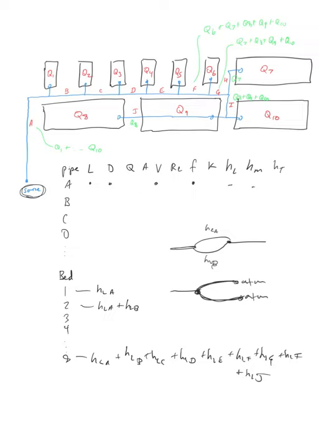What do you do in reality to combat that? Lots of things. You can change the design of the way the pipelines run. I drew one example here, but there are other ways that you could lay it out so that each branch, for example, has equal or close to equal length associated with it. You could add valves in the system, so you could add control. You could throttle flow down at certain points.